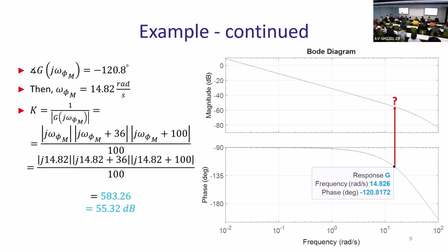So how does gain margin play into this? You are not moving that point where it was 59 degrees phase margin. You're just moving gain up or down in such a way that it will cross zero, and then this point will become your phase margin. This is the idea. So we picked that spot, not randomly, we picked it where your phase margin is the desired phase margin, and then we're finding the gain.